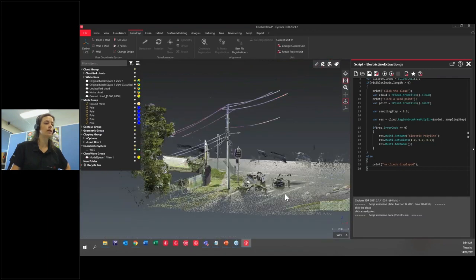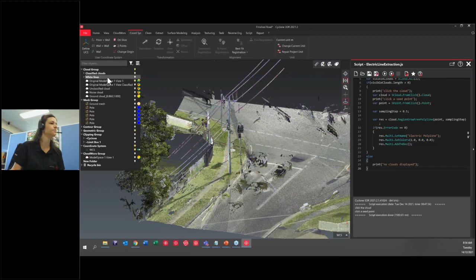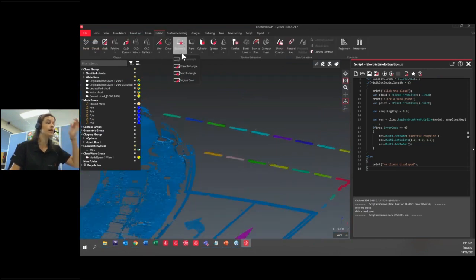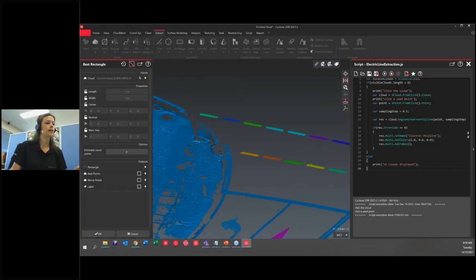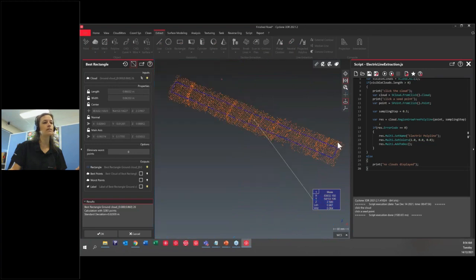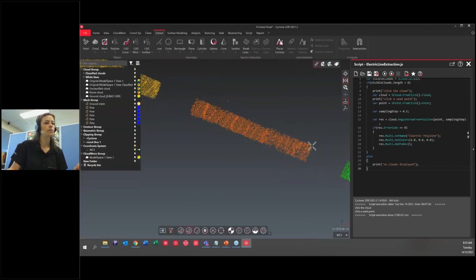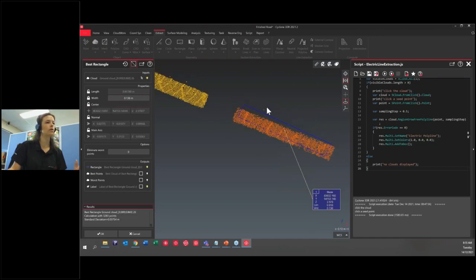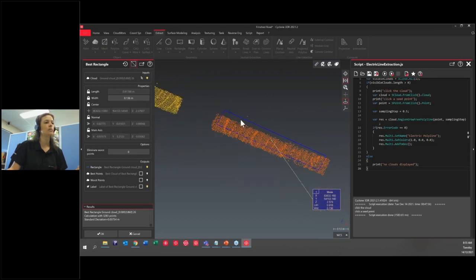So you could. There's one thing that I wanted to clarify and I didn't manage to. What's happening inside Reshaper is that if you have a best rectangle option here, it actually computes a best rectangle, which means it's not an outside rectangle. So I think the way to do that would be to measure, and you'd probably know what the width should be, like 136, and then we can potentially just force that here, the width and then the length as well. I think it's going to the right because I've got a few points here, but that would be the way to go.